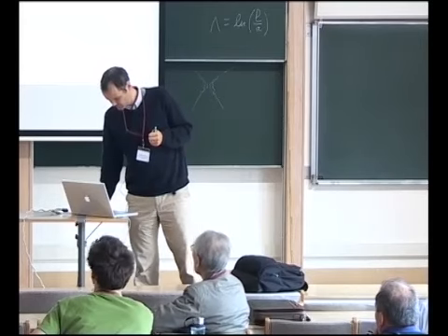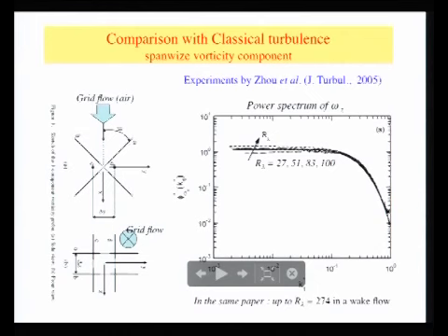One other piece of information which is relevant here is that these kinds of probes are not able to measure vortex lines which are pointing in the direction of propagation of the wave. So it is an anisotropic probe, and vorticity is only measured in two dimensions.